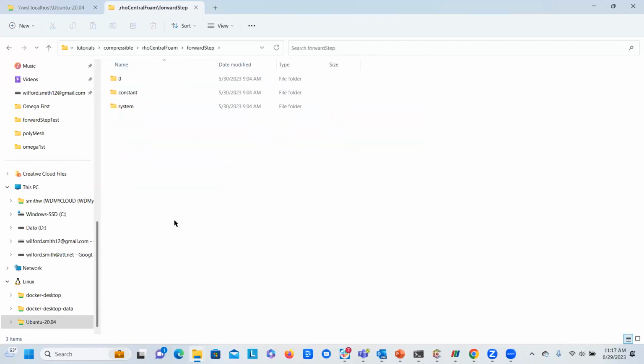What would generally happen is, if I go back and look at OpenFOAM, it generates a case structure that includes a system directory that I have to populate and a constant directory, which I also have to populate. These are text files that have to be populated using the OpenFOAM system or whatever system you have available to you. Okay.